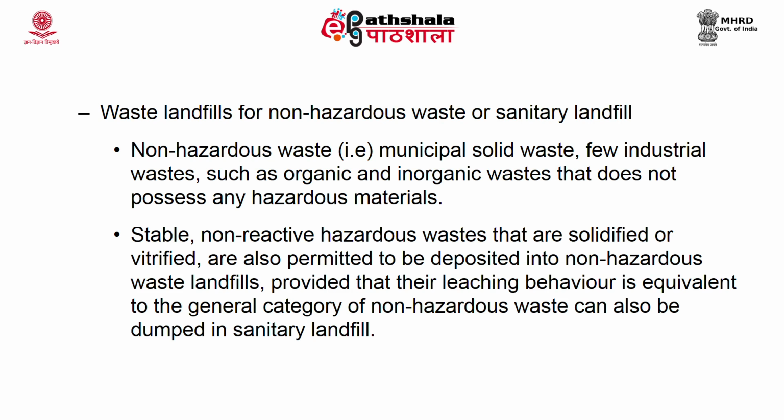Stable non-reactive hazardous waste can also be used, but in a solidified or a vitrified manner, and they can be deposited into the non-hazardous or the sanitary landfill in that form. It is solidified or vitrified so that it does not cause any leachate generation, and the leaching behavior is equivalent to the general category of non-hazardous waste.